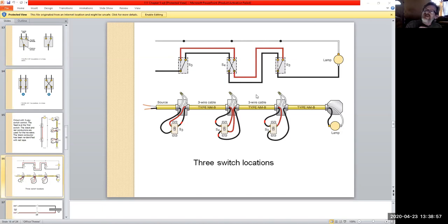If not, you'll get it where the light will turn on, but the other one won't turn it off. That kind of thing. Yep, you've got a reversal of your wiring going on in there. That's very, very common home residence wiring where the guy knows just enough to wire stuff up but doesn't really know what he's doing. A lot of homeowners really flub up on the three-way connection, if you will.